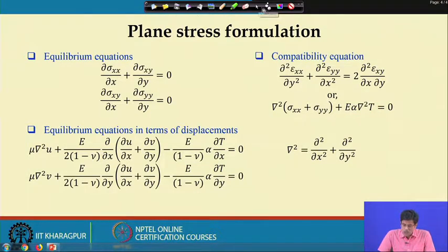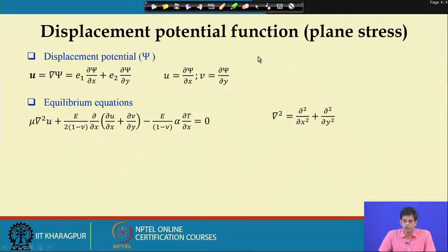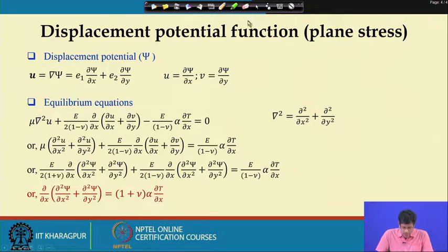Now, once we have this plane stress formulation, we can move to the displacement potential approach, which is essentially writing the displacement in terms of a single displacement potential function, psi.